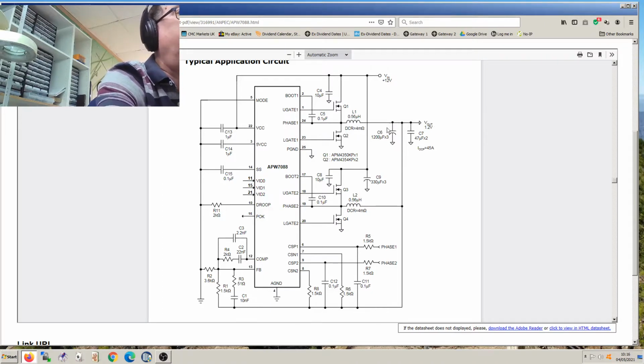There's a little feedback coming in through here, which through a capacitor and then a 1.5 ohm resistor, and then through another 3.6k resistor to ground. And effectively, both of these would have to be short, and we know resistors don't tend to fail short; they tend to fail by going high resistance. If you didn't know that, you should watch the tutorials I did on resistors, and then you would know that. So it's not very likely there's a problem there.